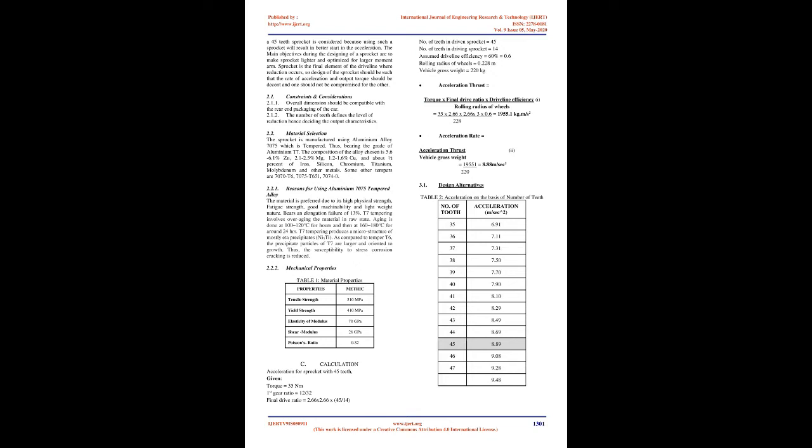The sprocket has been designed as per the use and performance required by a Formula student vehicle. The preferred parameters are as follows. Vehicle performance plays a major role in the dynamic conditions, thus the sprocket used here has been designed in such a manner that it can provide the maximum efficiency. The sprocket is designed to bear the load of a 390 cubic capacity (cc) engine and 42 brake horsepower (bhp).